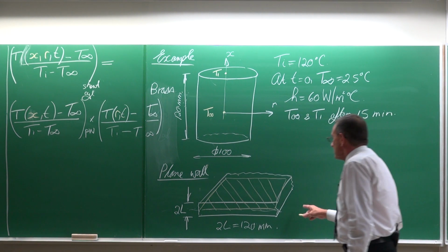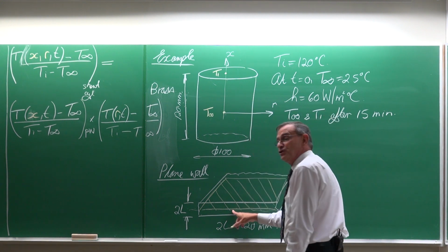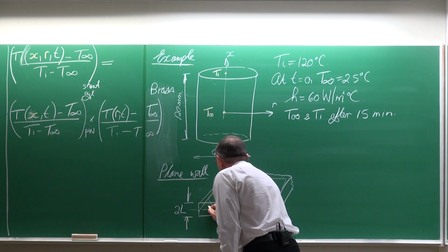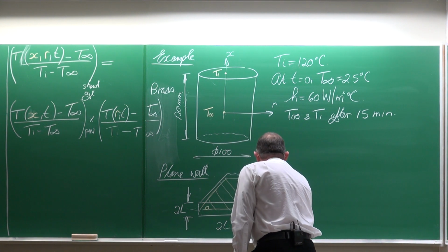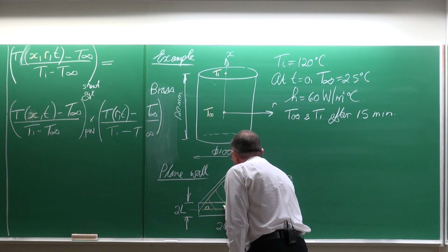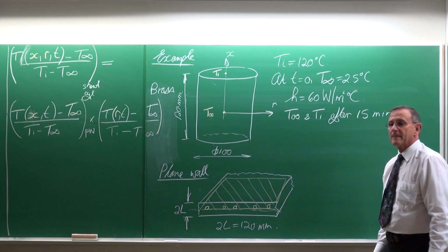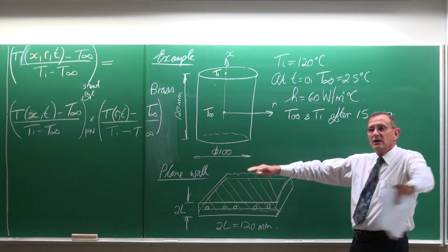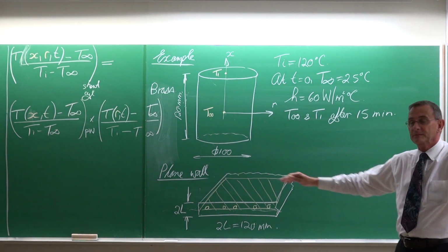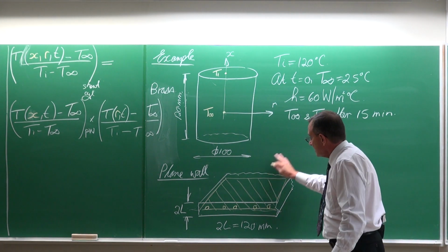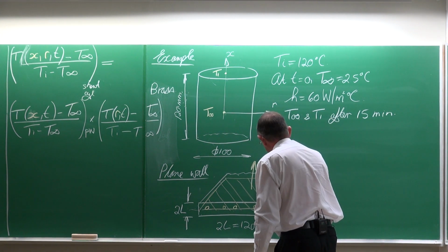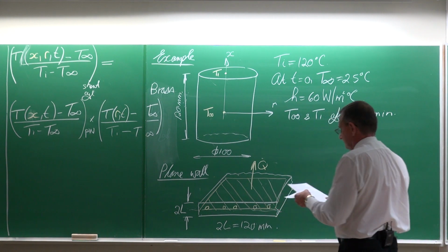If we have previously determined the temperature 0, then it would be the temperature on that line. And it wouldn't represent it actually on the end of it, it will represent it right through the body. Because there's no heat transfer in this direction, all the heat transfer would occur in that direction. It's one-dimensional.